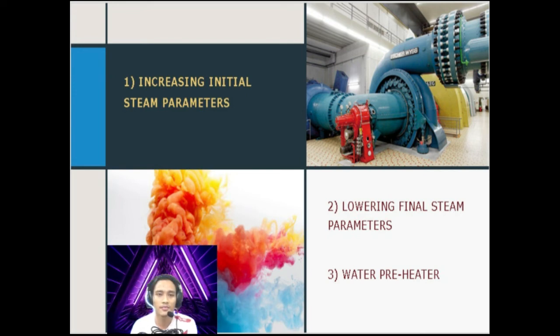As discussed above, the efficiency of thermal power plants could be improved by increasing the initial steam parameters. High volume, high parameter supercritical and ultra supercritical thermal power plants have proven stable and effective for large scale commercial power generation. Supercritical power plants can attain an efficiency 2 to 3% higher than subcritical power plants, while ultra supercritical thermal power plants boast an efficiency even 2 to 3% higher.